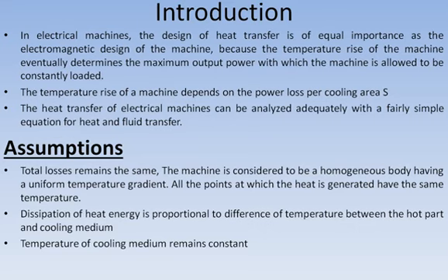Even though in actual practice it is not like that, we are making an assumption that all the points at which heat is generated have the same temperature. Next major assumption is the dissipation of heat energy from its surface is directly proportional to the temperature difference between the hot part and the cooling medium. Third assumption is the temperature of the cooling medium remains constant.